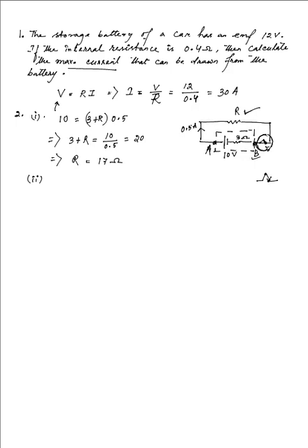That terminal voltage is simply equal to, as you know, V equals R times I. That is the resistance that was just obtained, 17, times the current that is flowing, 0.5, and that is why this value comes out to be 8.5 volts. That is the terminal potential difference across the battery when the circuit is closed.